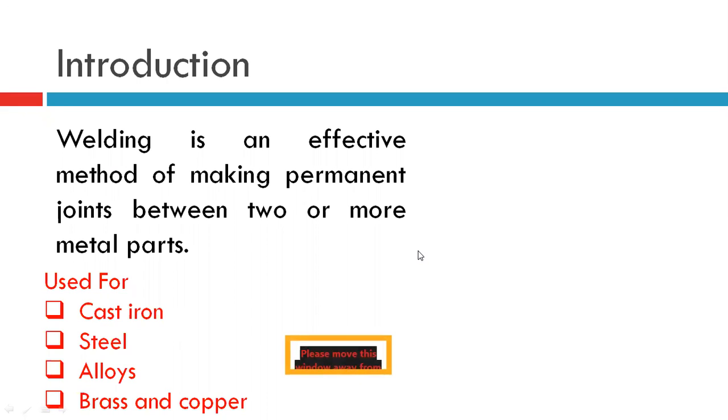Apart from that, welding is one of the easiest methods to join two different parts, and we can very easily move the welding machine from one station to another or directly to a field. In the case of riveting, it is very difficult to go to the field and join two metal parts. That's why in industry, particularly the sheet metal industry, welding is a very important part of the process. So how should we mention it in our drawing?